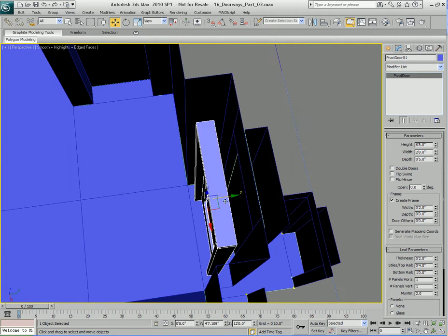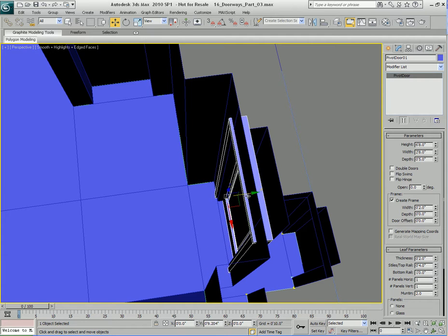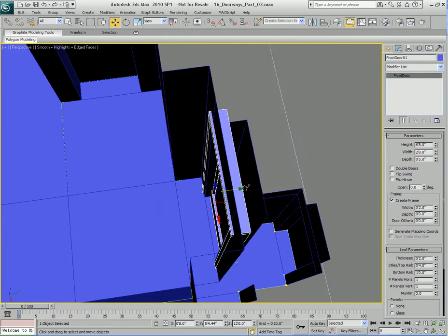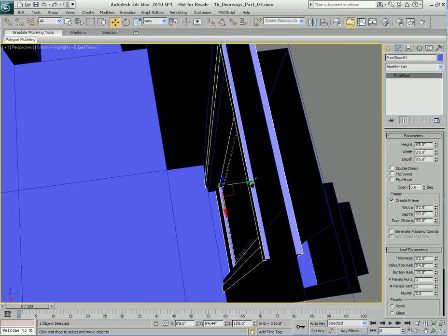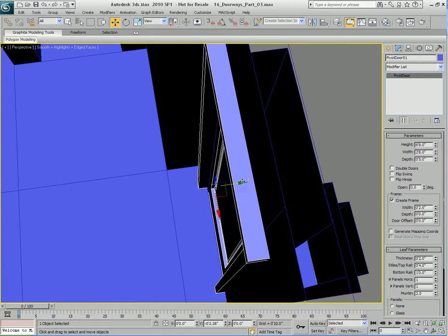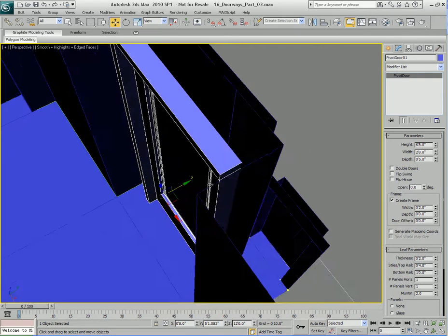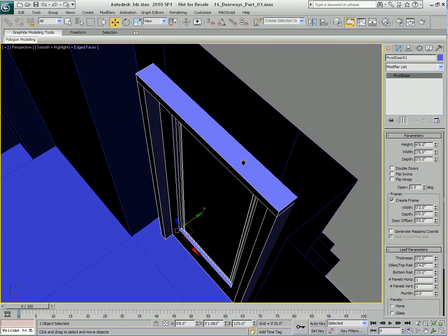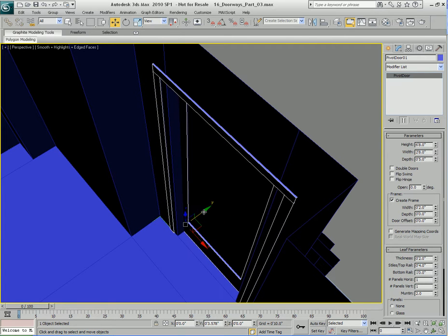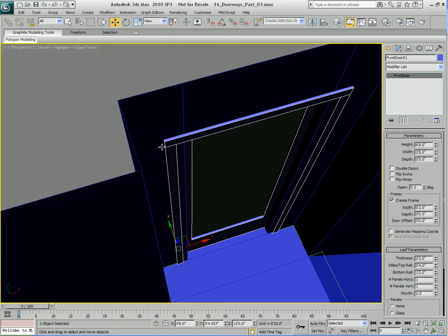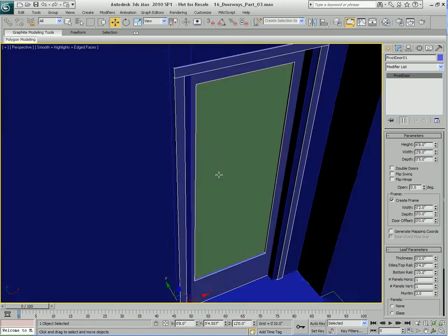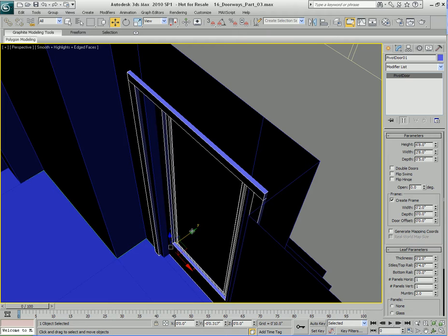Now the only thing I have to do here is take the door and place it into the wall right there. Now this is okay to eyeball. You can go ahead and just kind of freely move this. It doesn't have to be precise because we're just moving it in the Y axis. You can place it here, but if you place it here, you can see the door frame is sticking out a lot from the wall, and that doesn't look right. If you go on Google Images and search for photographs of interior doors, you'll notice that they very rarely look like this. They're usually farther in like this. So the door frame just sticks out a couple of inches from the actual wall, just a little bit like that. So maybe I'll put it to about right there,